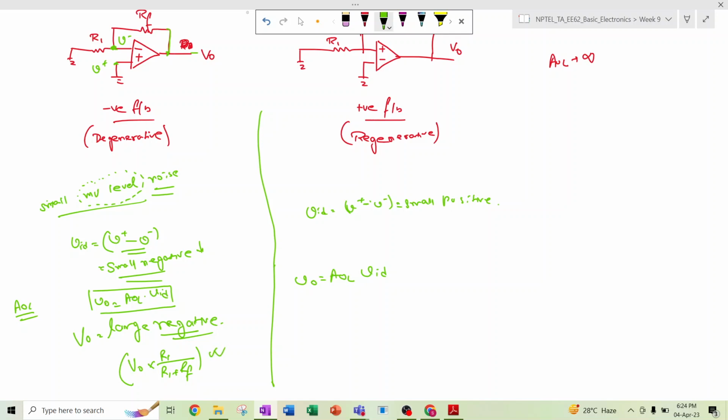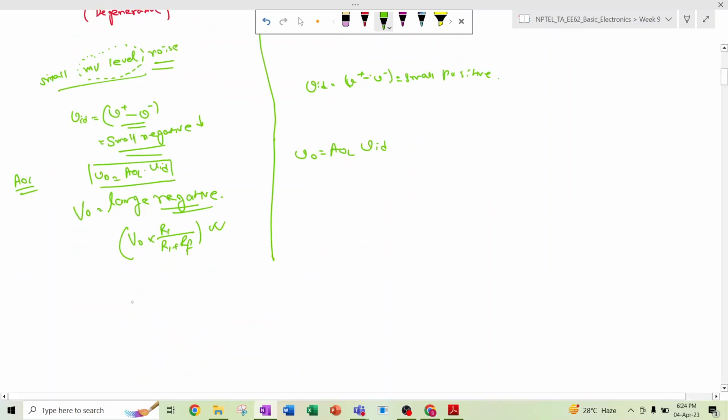This part is being fed to the input terminal of the op amp, so this is again a negative voltage. So a fraction of negative voltage is adding up with the initial positive noise. This is known as degenerative action, because the signals add up in opposite phase.